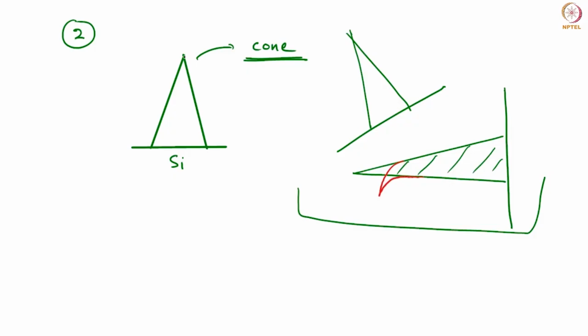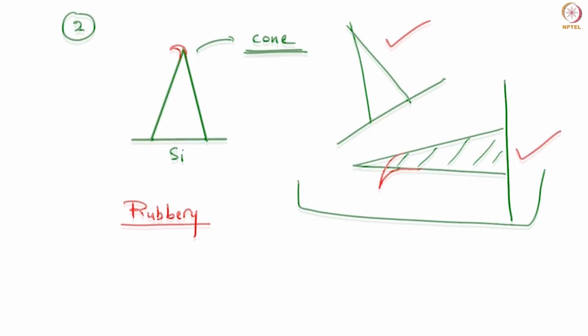Or even if the polymer goes through too much of a liquid state, so not a semi-solid but rather a viscous liquid type state, in that case, even when your tip is standing up, you will find some sort of bending. But if that is not the case, because there are many polymers that just go through a rubbery or semi-solid state, not a liquid-like state, in that case you will need to place your sample in such a way that you can observe some sort of deformation afterwards.